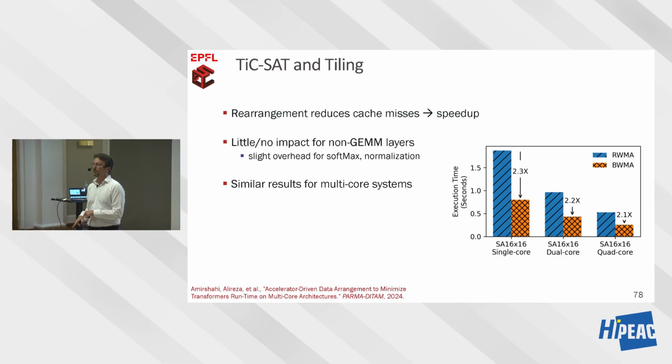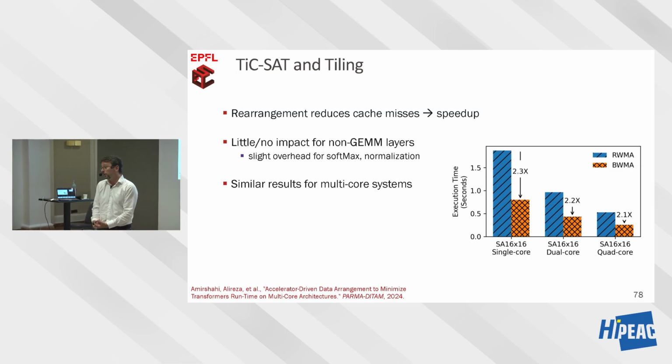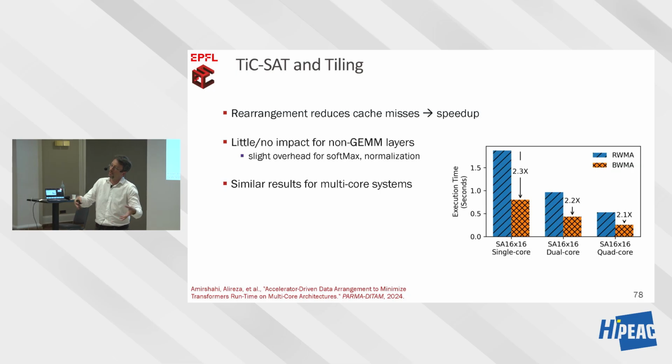So you can store the data where it is needed. Having said that, when you are processing, this is a custom functional unit, so it lives in the processor pipeline, and yes, it has to abide by all the cache misses which you may have, and so on and so forth. But by doing this tiling, you are actually minimizing the overhead of the cache hierarchy.